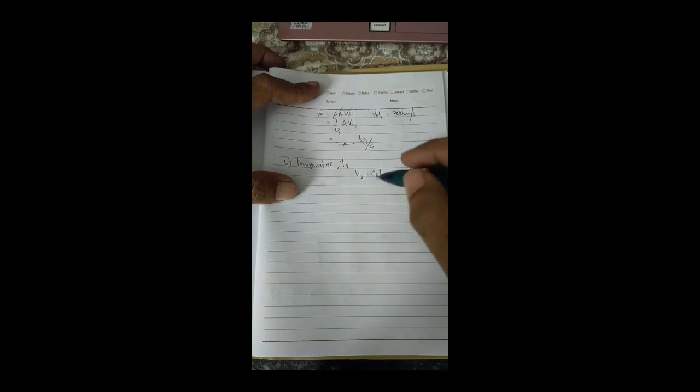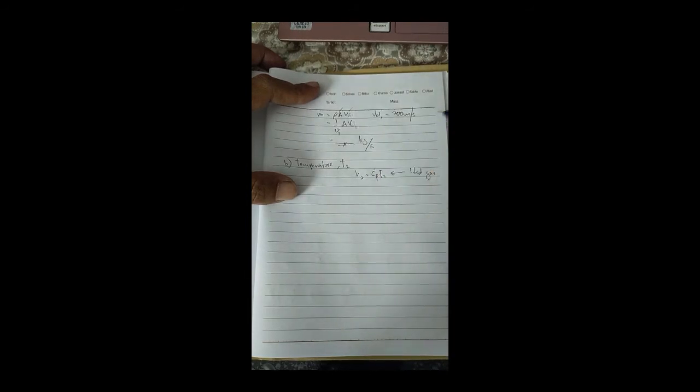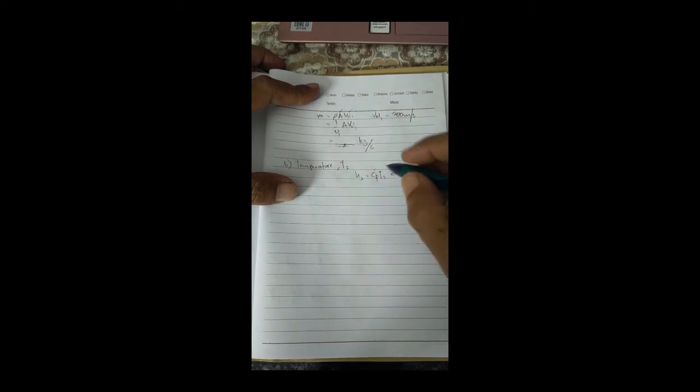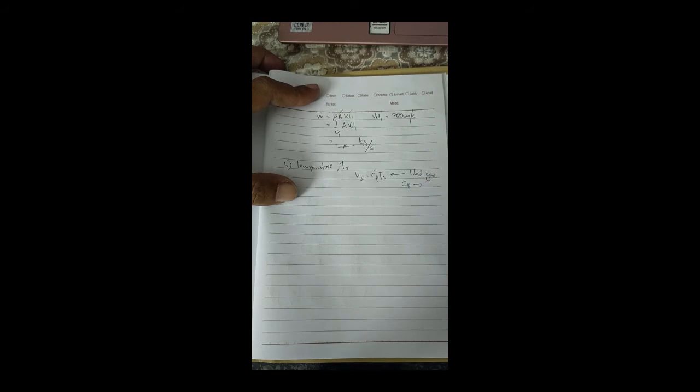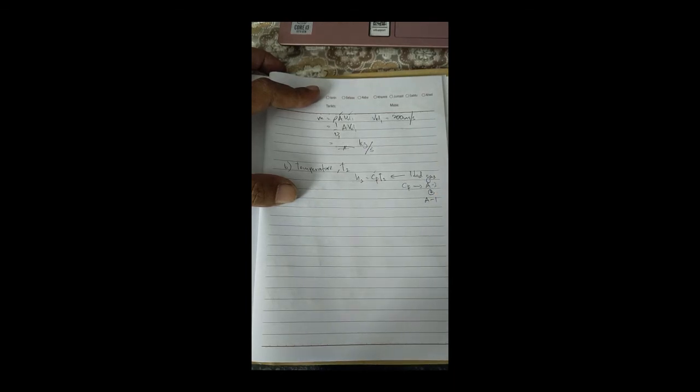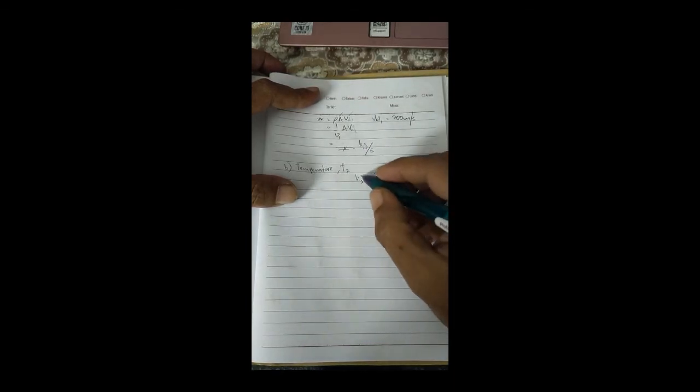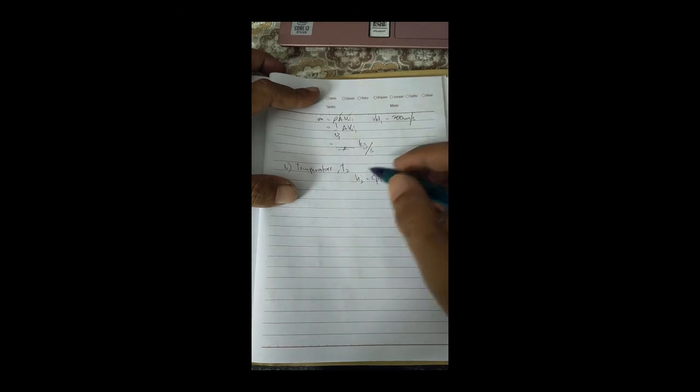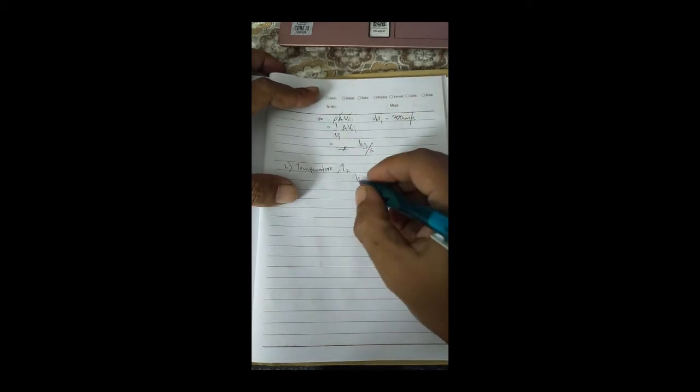Cp is a constant, so you can find Cp in table A2 or A1 in the appendix. So we can determine the enthalpy, but currently we don't know enthalpy 2. So firstly we need to calculate H2, the enthalpy 2.